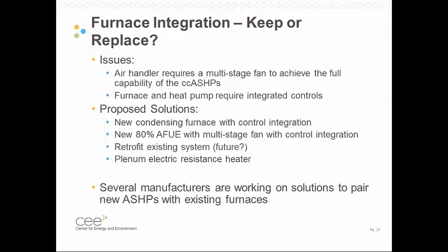With these newer systems that have a wider range of modulation, can heat at cooler temperatures, and have a lot more integration on the control side, it's really important to have a backup furnace system that talks with and has the capabilities needed for the heat pump system. And so right now the path to achieve that for manufacturers is to install a new furnace at the same time as the heat pump system. And you can imagine that that has a significant impact on the total installed cost. So we looked at a few different options for installing this system.